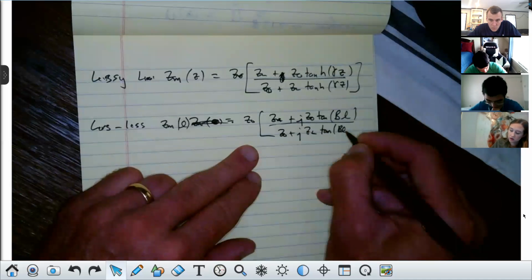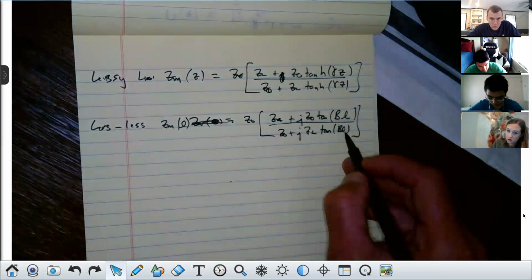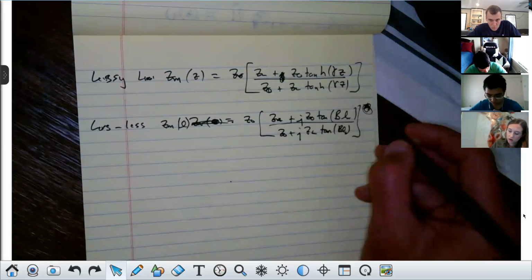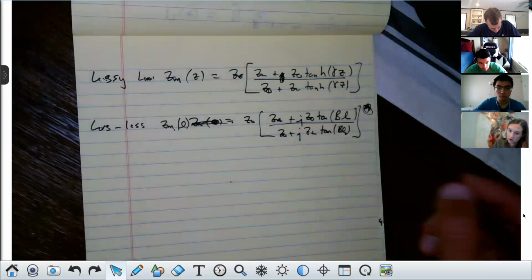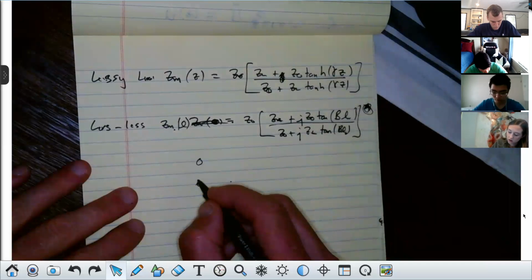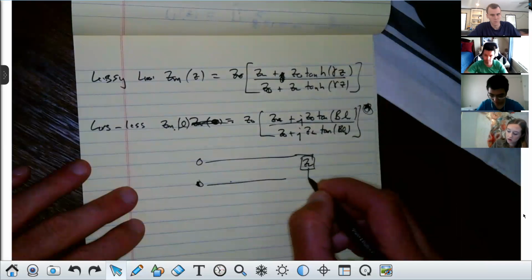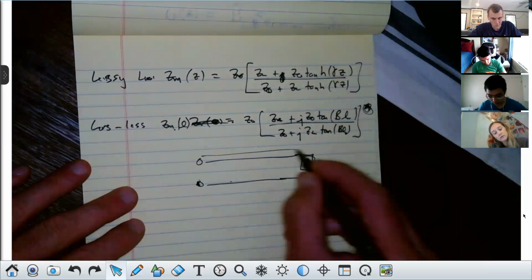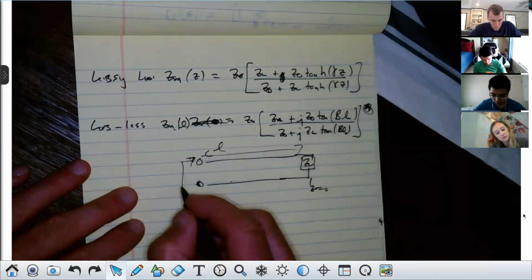And I'm going to explain something here. That value L is going to be a strict positive number. Remember, Z would be minus L, but L is just the length in meters. And this is the input impedance. This is the one we use over and over again right here. It is the input impedance to the line. So if I have a line, and there's a load here, the load is at Z equals 0, and the line has a length L. Then what I'm looking at is the impedance right here, Zin to the line.